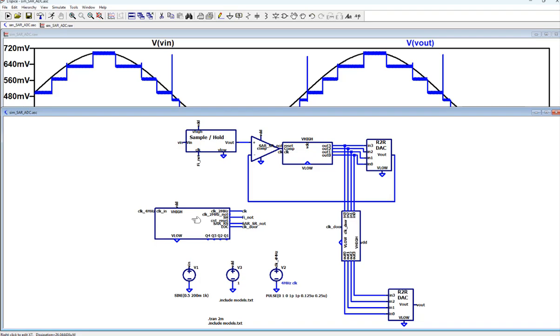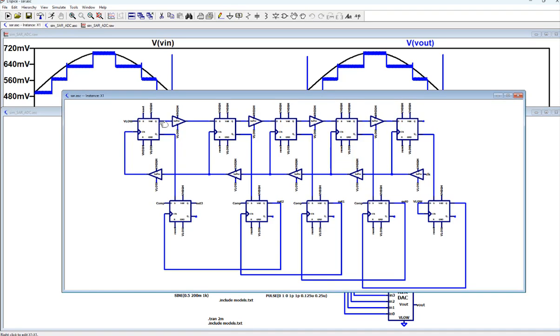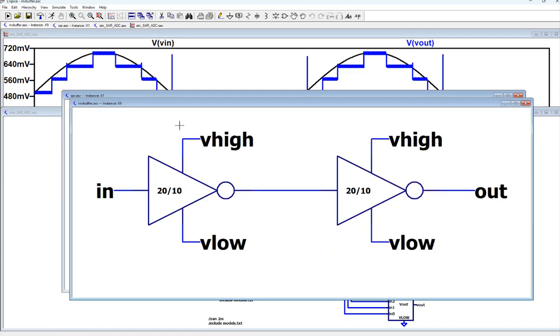For example, I had issues here, right? So you can see this is the sequencer on the top, just D flip-flops, and code registers at the bottom. And eventually I found out I have to use a buffer in the middle. The buffer is nothing but 2 inverters. It's basically just adding more channels to source current from the source and ground.